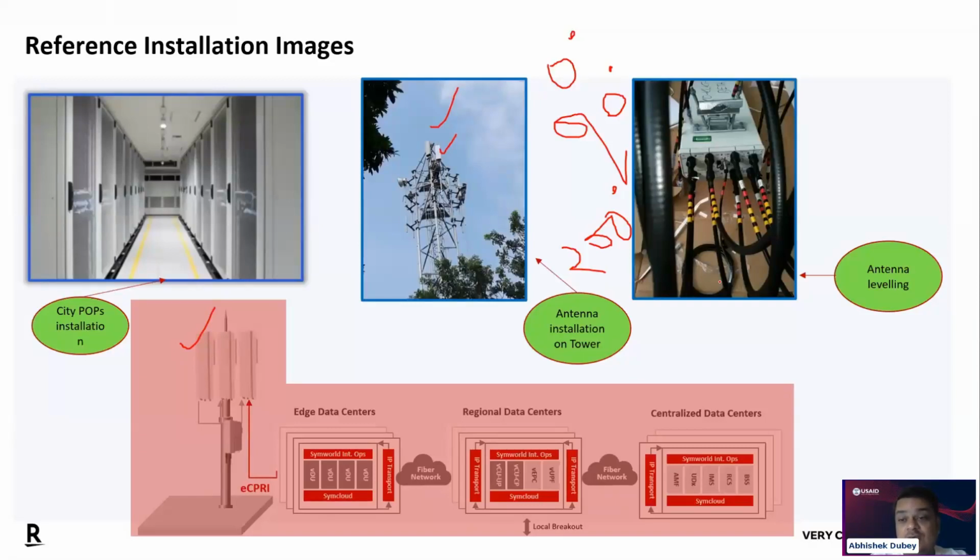So always do weatherproofing or waterproofing wherever is required. Okay, wherever there is a connector, there is a certain weatherproofing that you need to follow. Otherwise, if there is no weatherproofing, there could be water ingress, and that could cause losses. So you may face higher recoveries if you have not followed the steps during the installation.